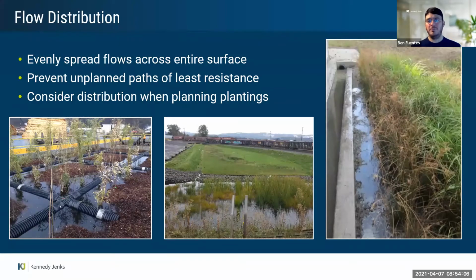Ideally, you are trying to avoid pipes or closed conduits. Ideally keeping things open channel or just at the surface can help facilitate O&M over time: the ease of inspection, ease of cleaning out your distribution system. But a pipe system can be helpful for getting the water across longer spans.